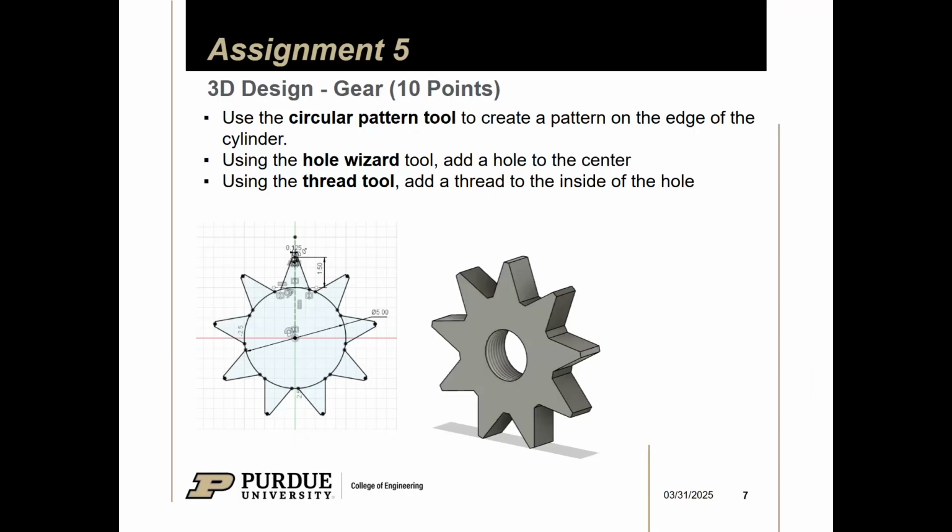But when it comes to specialized holes and threads and stuff like that, that is considered bad practice. And the reason is because when you go from design to manufacturing, you want to give as much information to the person manufacturing your piece as possible. Especially when you're in industry, a lot of the time you might design something, but you're not going to be the one making it.